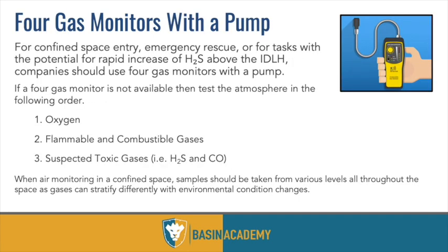So then you have 4 gas monitors with pumps. You can also do single gas monitors with pumps. Again, there's a lot of configuration, but essentially they're also called direct reading measurement devices. The end of that hose has that black tip, and it's going to draw air into this monitor and read it from an area away from you. So you're not right in it. Some guys use their personal gas monitors for this. It's not effective, doesn't work. The amount of time necessary to read, depending on how quickly you're moving that around, may or may not work.